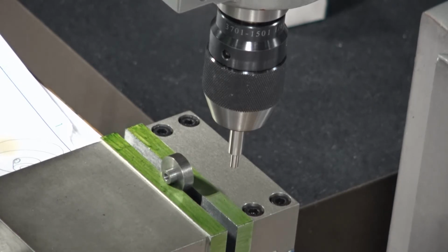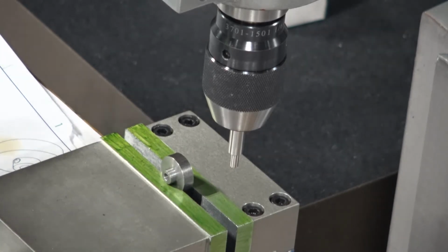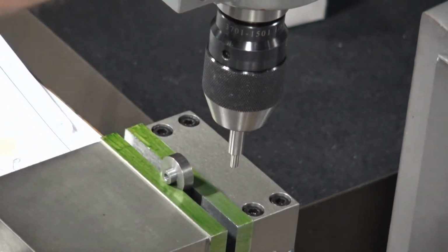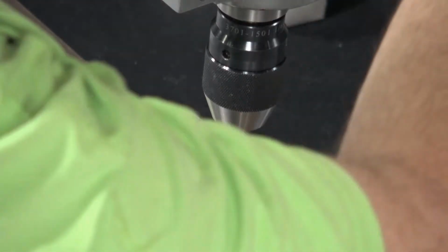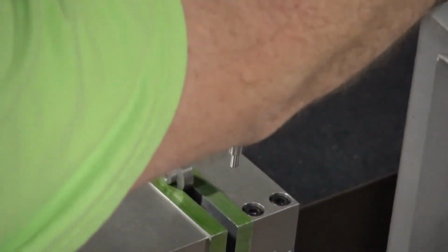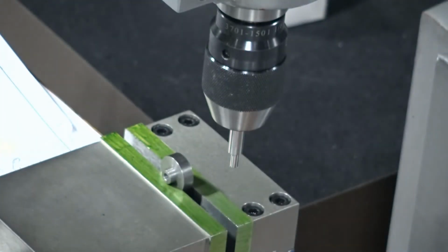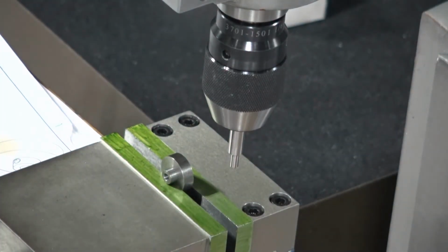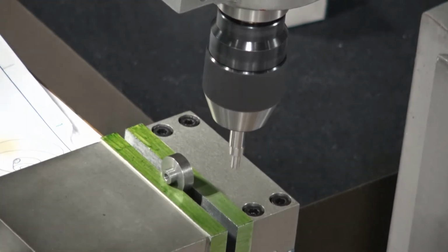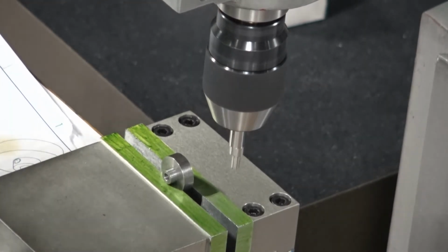And when we're threading, we don't actually turn the spindle on. Now I've previously checked and made sure that we were on our top set of belts or pulleys inside the motor compartment. Cover that guy back up. And we're going to be on forward high. If I go on forward high, that's where we're going to want to run.